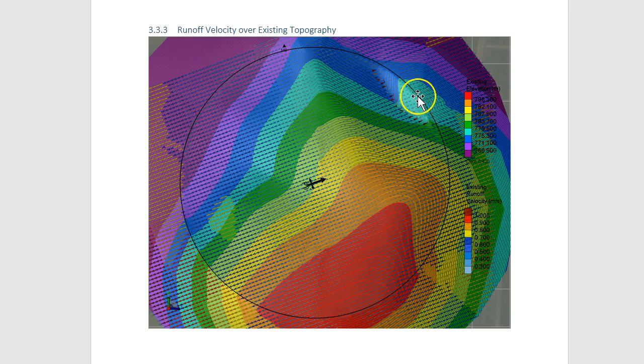And if the furrow direction was switched around to this 70 degrees, then it's probably still wise to have some type of sediment trap down in the lower part of the field, as water's going to drain around here. You'd need a drain around the edge of the field to take it down to a sediment trap before it runs into the watercourse.